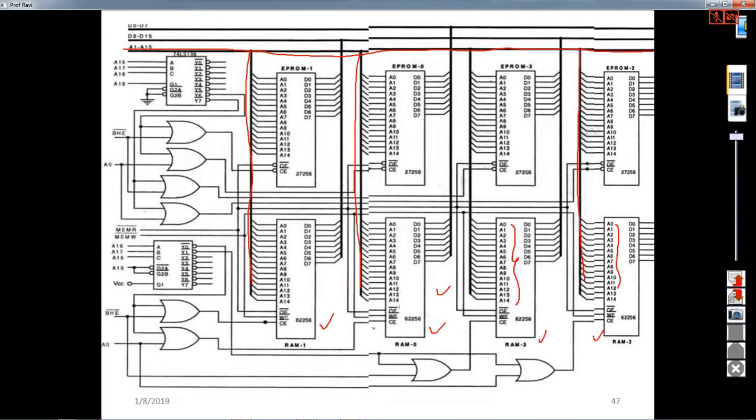So then this is RAM 0 and RAM 1. So this is 64K, so total 64K plus 64K, 128K. That means you are going to interface 128K of RAM. But the only thing is you don't have direct 128K, you have 32K chips.